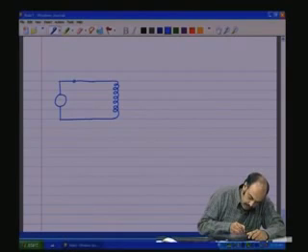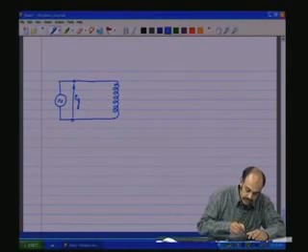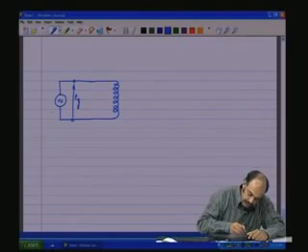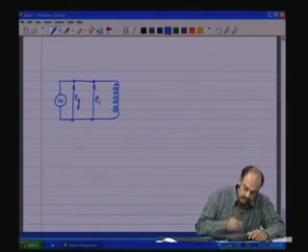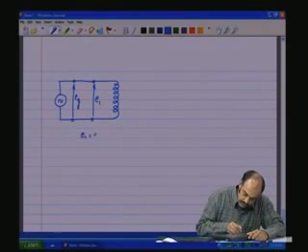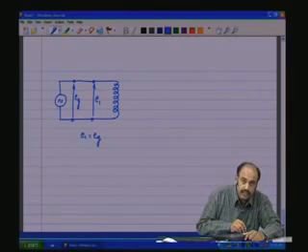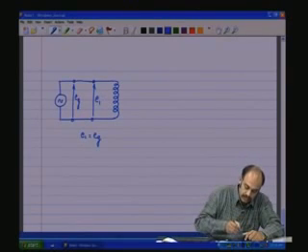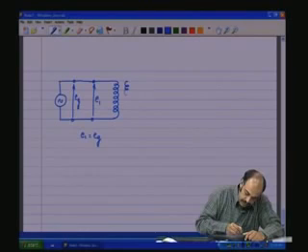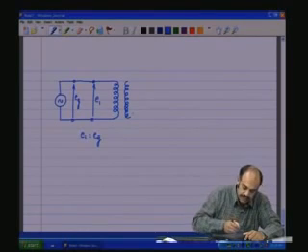I will still name it as EG, the generated voltage or the applied voltage. This is the generator voltage which is applied, and there is an induced voltage across the primary. Effectively E1 equals EG always at every instant of time. However, to distinguish between the generator voltage and the induced EMF, let us have this distinction.